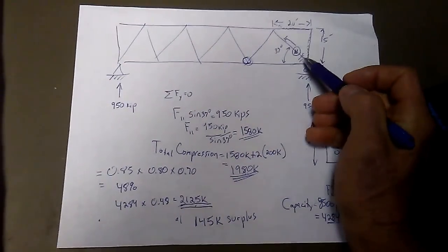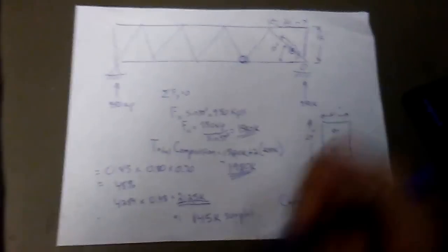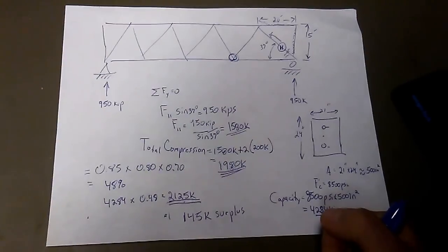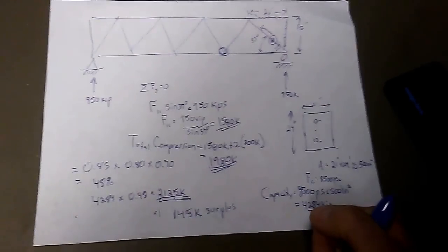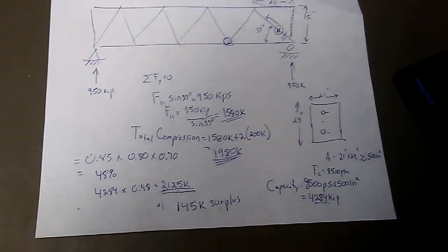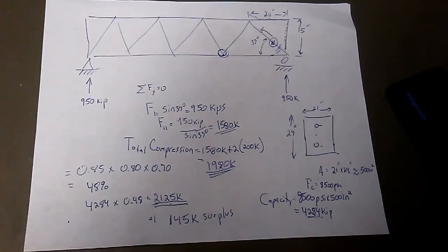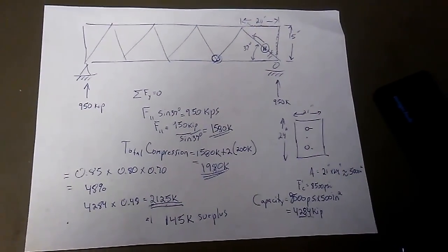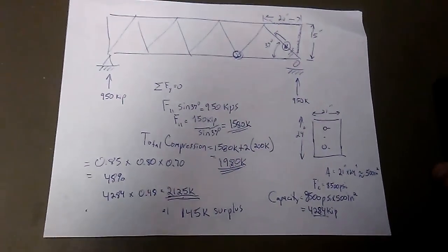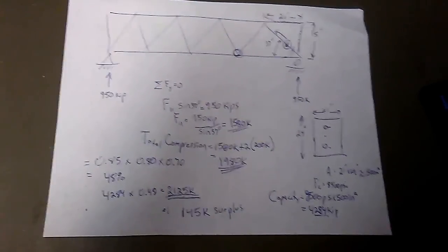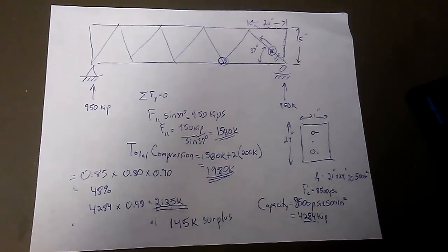The cracks in tension at this location in a compression member are not going to grow. Because the member's in compression, the cracks are stable. They will not grow wider because they're being squeezed, and in reality, the cracks would potentially get smaller in width, and they were not a safety issue. So I agree. As an engineer, if I had been the engineer, I would have made the same call. I would have said those cracks are not significant, not a safety issue.